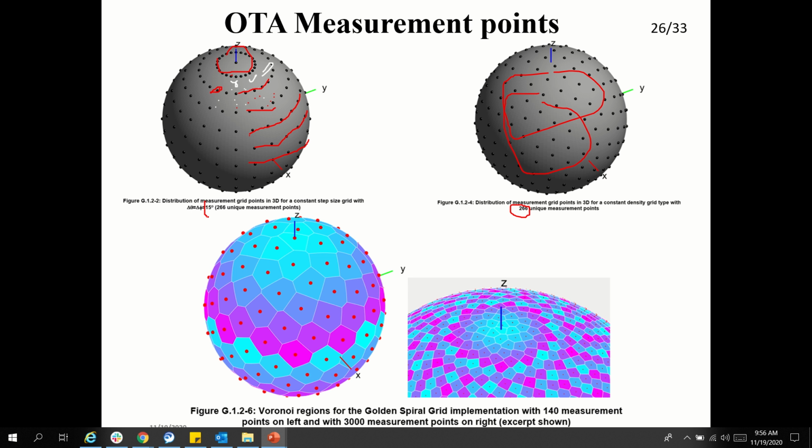What they are doing is, in the phi plane and theta plane, they are keeping your device and capturing the power at a 15-degree interval. Which means you have your device, and you have the x axis and y axis. At each 15 degrees you will have one point. You have to imagine it is 3-dimensional, so the difference between this point and this point will be 15 degrees.